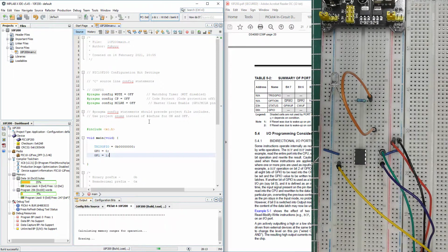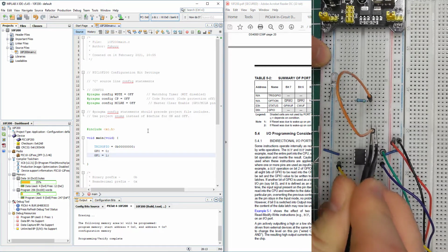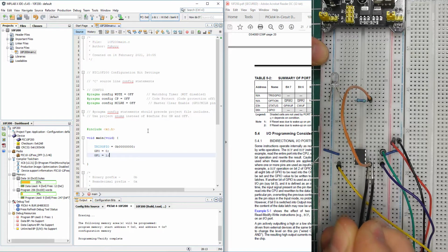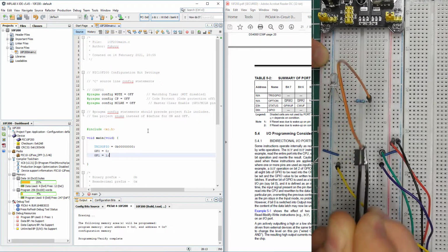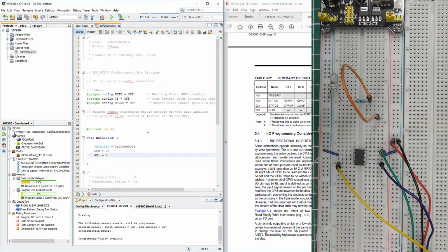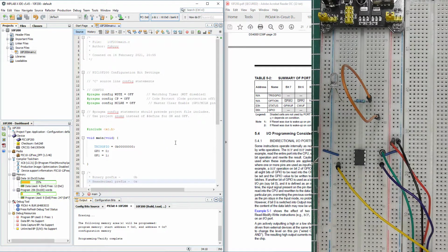Okay. Now build and program, build successful. So now what I'm expecting to see is on the GP0, according to our new program, there should be nothing. Yes. GP1 still should be high. There we go. So that's what we can do. Later on in the next videos we'll have a look at the bigger PICs. They're gonna go bigger and bigger. Instructions will be slightly different, and we're gonna start using mixed binary and hexadecimal commands just so we can practice.